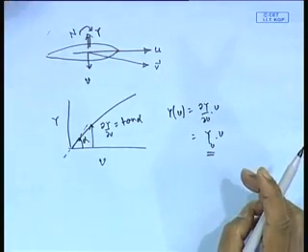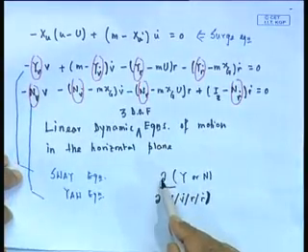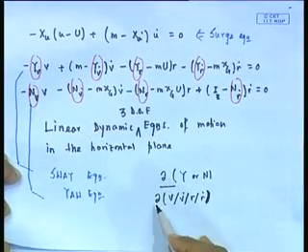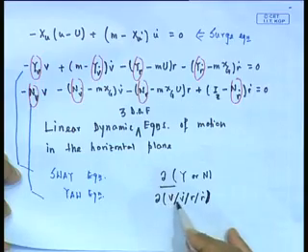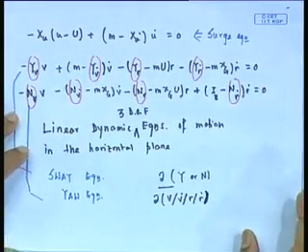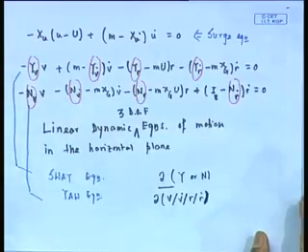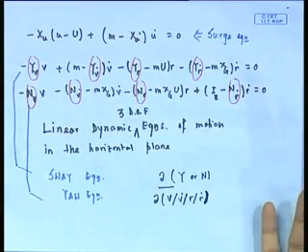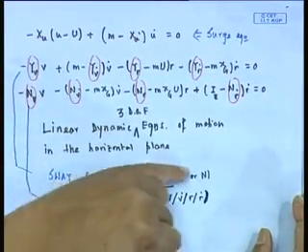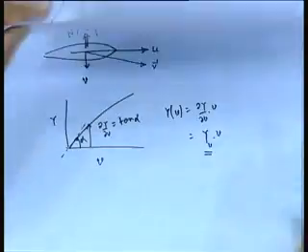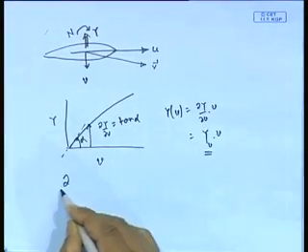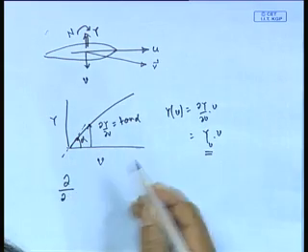the rate of change of hydrodynamic forces or moments against any of the velocity parameters, these terms are known as hydrodynamic derivatives, because they are derivatives of the hydrodynamic forces and moments.